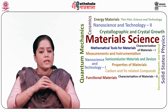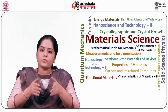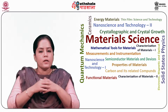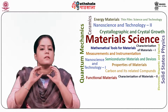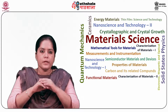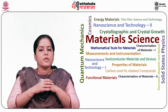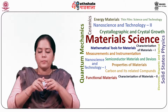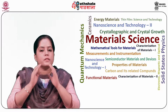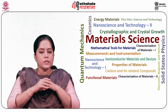Also, ALD is a very slow process and can be effectively used for substrates used in microelectronics and nanotechnology, because thick atomic layers are not needed. There are some chemical limitations as well. Precursors which are used should be volatile but not subjected to decomposition. So this imposes a limitation on the substrates that can be used.